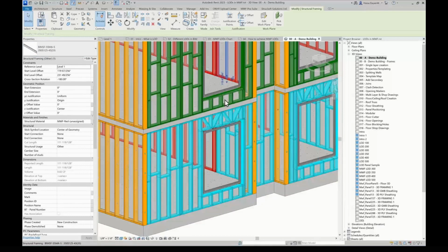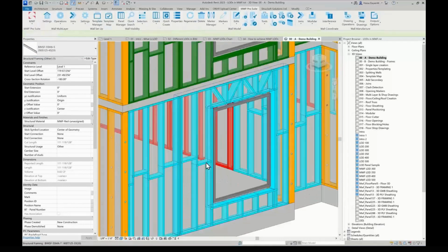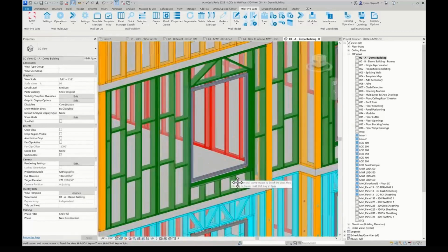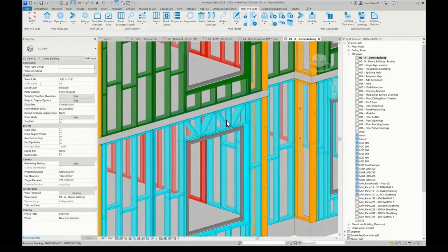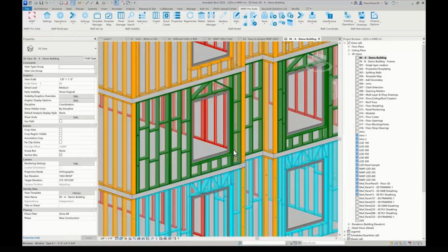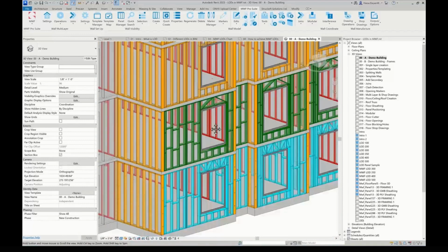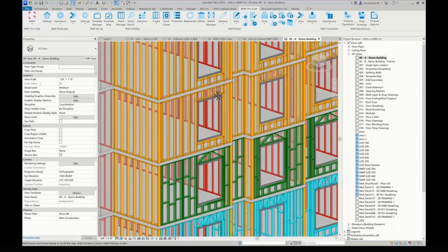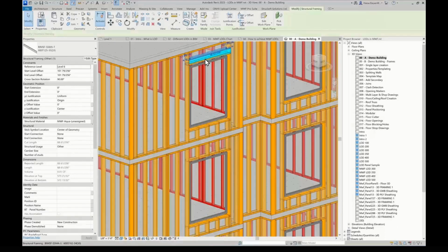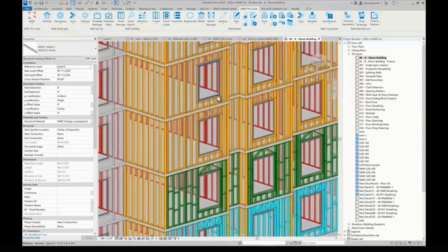and you can create a specific template for that interior wall. Other details include adding the horizontals that you need, for example, and very importantly, the opening details have to be clearly specified in this level of detail. So over here, you'll notice in this template, we're using a specific header type, and here in this other floor, we're using another header type. This opening detail over here is completely different, and this one here is also different. So it's very important to specify what you want to do with your openings.